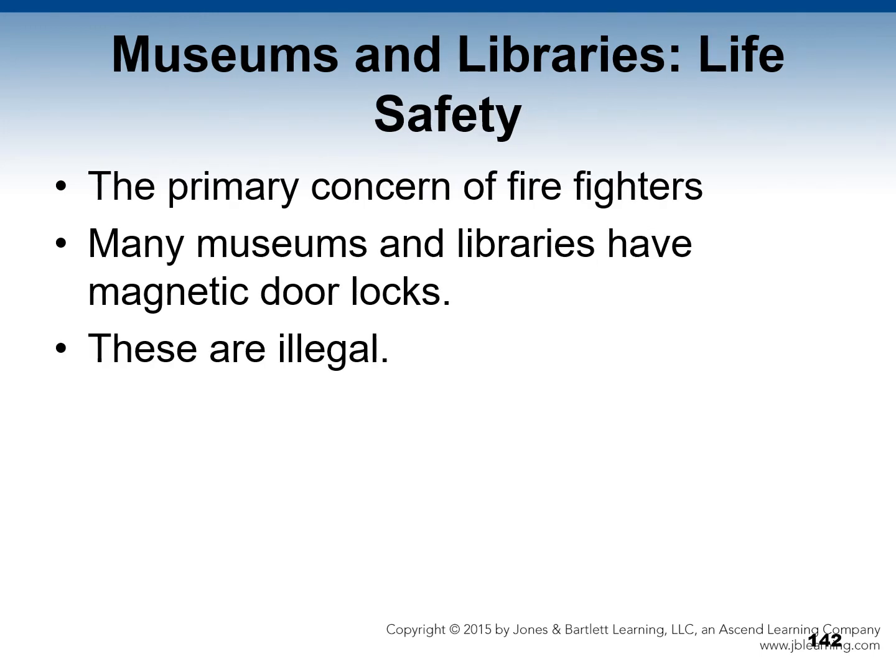Life safety is a factor in museums and libraries, of course, and the primary concern, in regards to life safety, is the protection of firefighters. And many museums and libraries have magnetic door locks. You'll also find these in hospitals as well, but these are illegal.